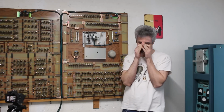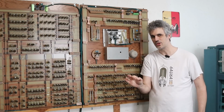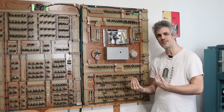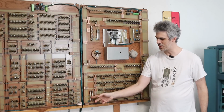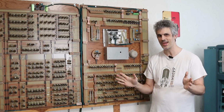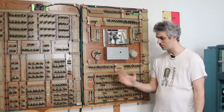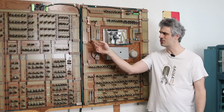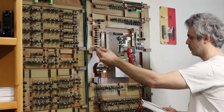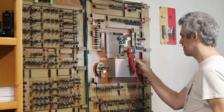Oh no. I put some extra pull downs on some signals over here that were not looking clean, and they are looking much better, but things on this end have now gotten exponentially worse. If I hit the button here, it runs through, we get a little blip on the output register, and then nothing else. I have no idea what's going on. The memory was actually working really well before, and it is still working really well. If I go through and single step it with the toggle switches here, I can put a bit into each location of memory and read it back out. So maybe we're hitting a speed limit problem.